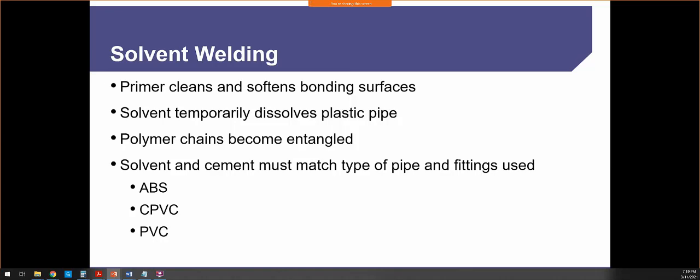Okay. Once you do apply the solvent to the pipe, you've probably got a good 5 to 10 seconds of workability with it. So we're going to spin the pipe about 1/4 of an inch or so just to get that glue to bind, and then we're going to set it into the position that we want. We're also going to hold that for about 30 seconds until everything starts to bond. All right, after 30 seconds, we're all set.